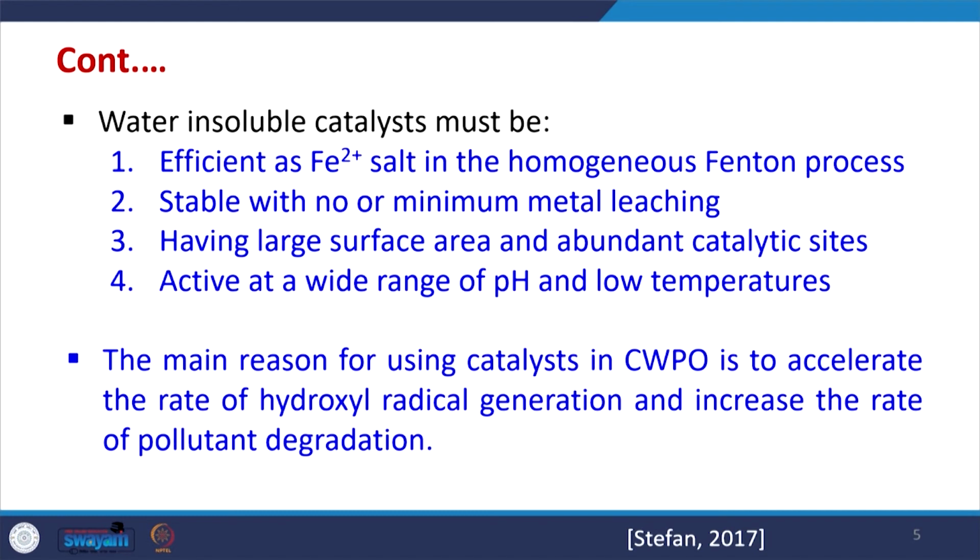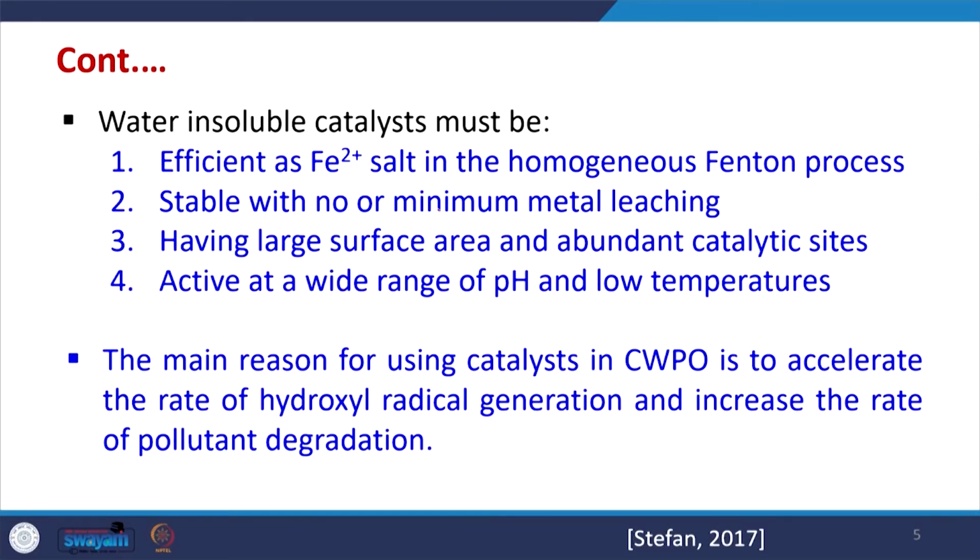Now, water insoluble catalysts used for treatment should have the following desirable characteristics. They should be as efficient as iron salt in the homogeneous Fenton process, but stable with minimal metal leaching. If we use any catalyst, it should not leach into the water, or if it does, it should be within the desirable metal concentration limit, and it should be usable for a very long duration.